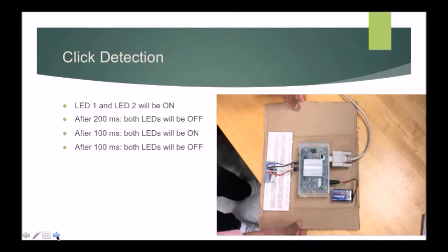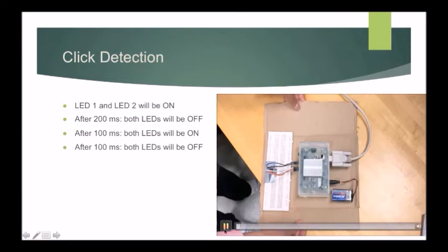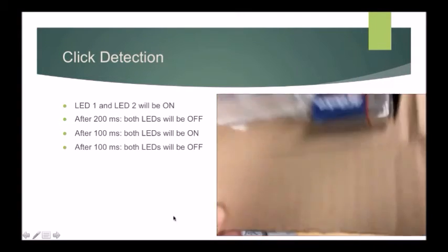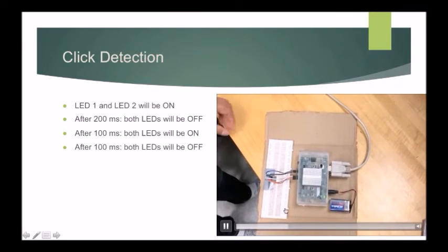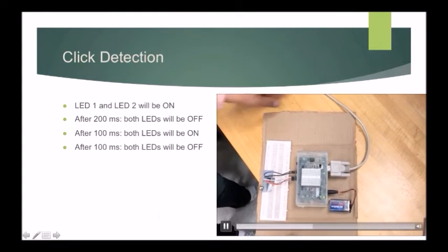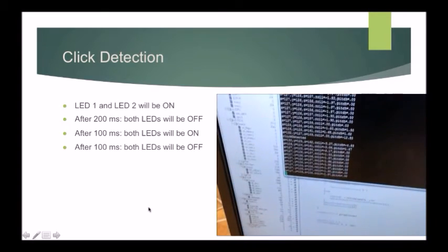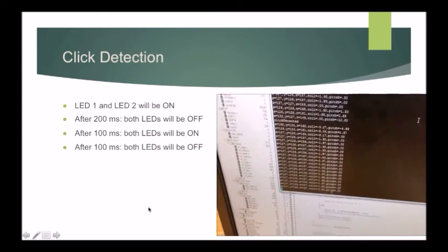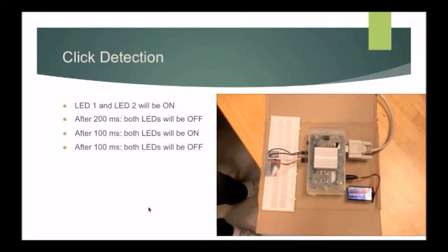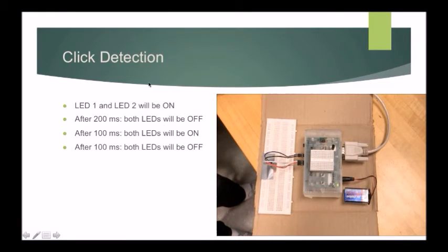Then click, as was discussed before, is how an accelerometer detects a motion. Here for a click, there will be a great change in value in the z direction, whereas a very mild value in the x and y direction. So when that pattern is observed, it will be detected that it is a click, and the following LED pattern will be observed.